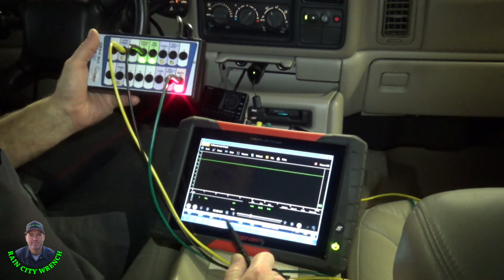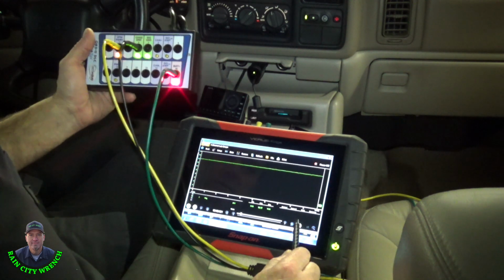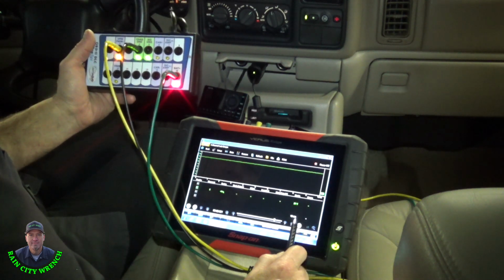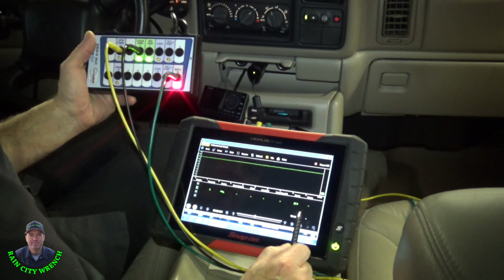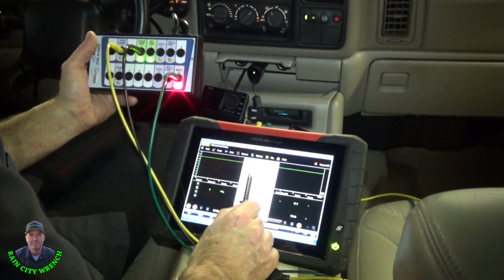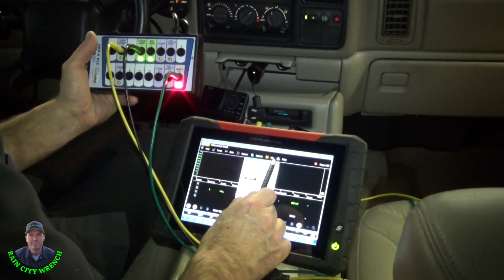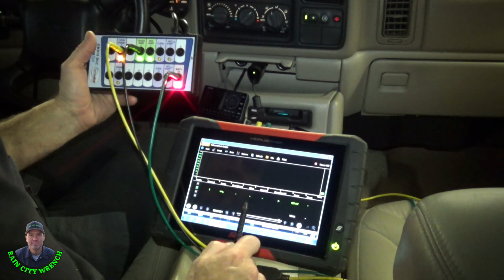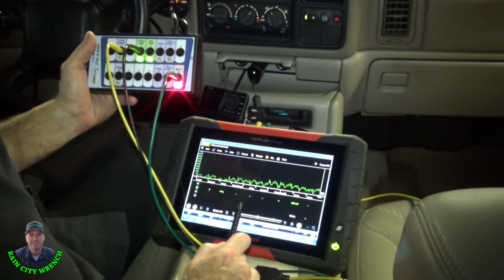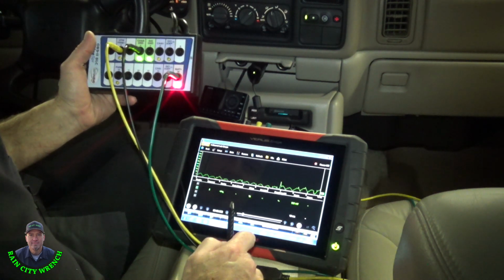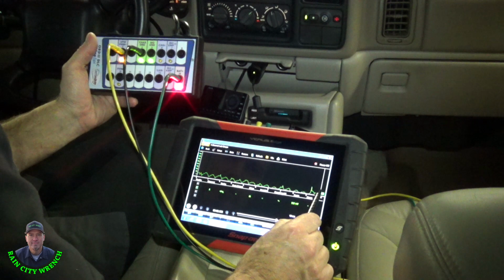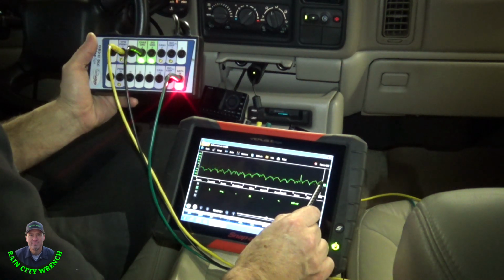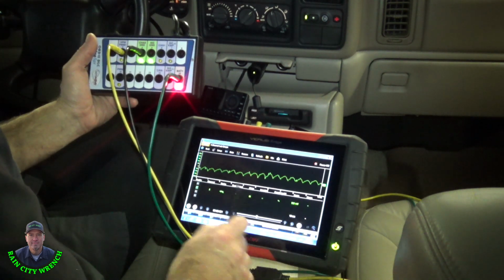Now we can check a diode pattern on this too. What we want to do is go to, let's see, it's been a while, down to like 500 millivolts. You'll turn your AC coupling on, filter on, and then we need to trigger this.